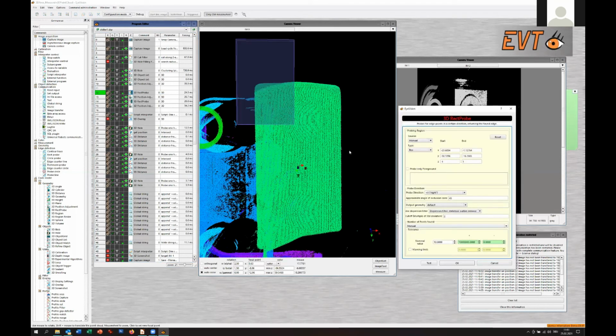If you now have a look at the Rect Probe tool, you will realize it opens up immediately. Why does it do this? Because the Rect Probe tool, in this case with the quick edit, doesn't execute the complete commands before. This has the advantage that you don't have to wait so long, but of course, the disadvantage is that the relations between the commands are not renewed. It makes sense only if you want to change some of the parameters, maybe the direction of the search position, because you saw, okay, this is wrong. For the next loop, I want to have a different direction.